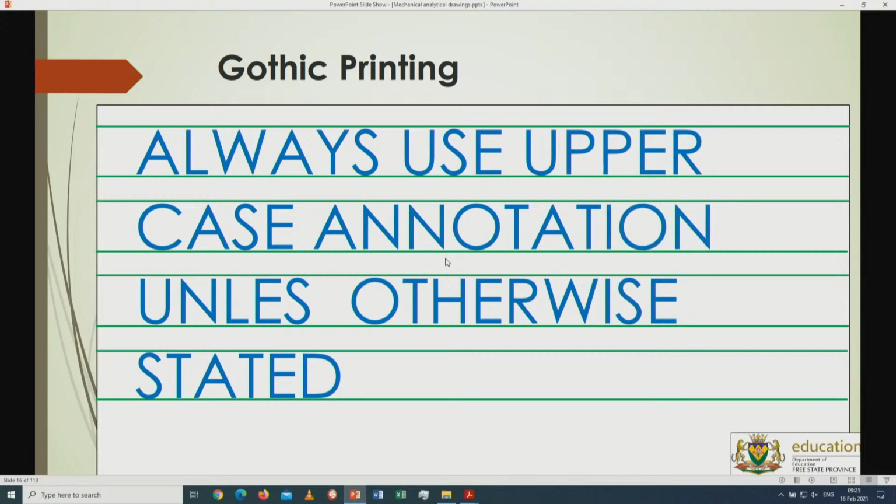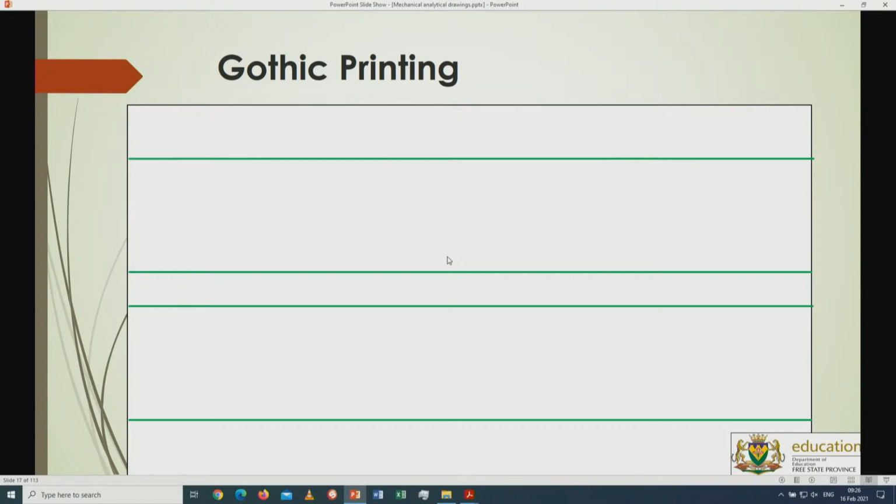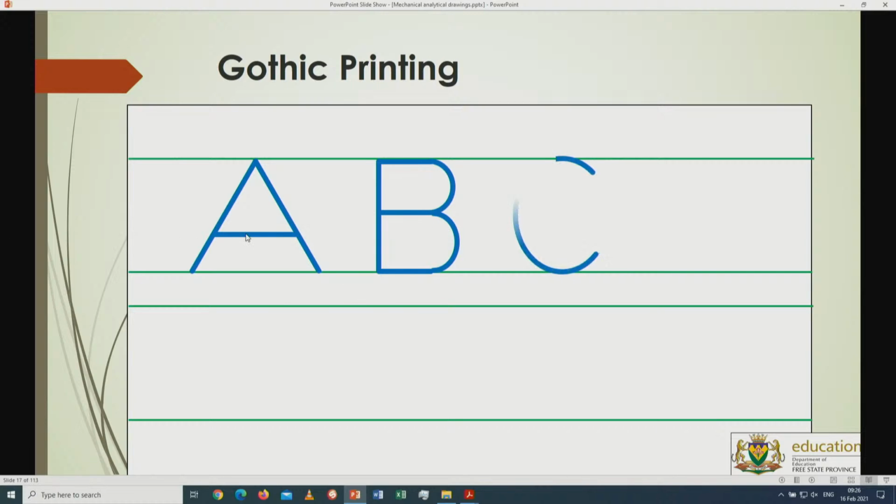Most of the time, unless stated otherwise by the examiner, it will be caps lock. In other words, using uppercase letters in that regard, so like you see in this case over here. And then of course, if you draw the letter, like I'm saying, it's drawing, it's not actually writing it. The wider you can go, the neater the drawing will look. Right, so the same with B. If you go horizontal for the top, middle and bottom part before you start curling it back, it looks much neater in the process. Right, so there we go.